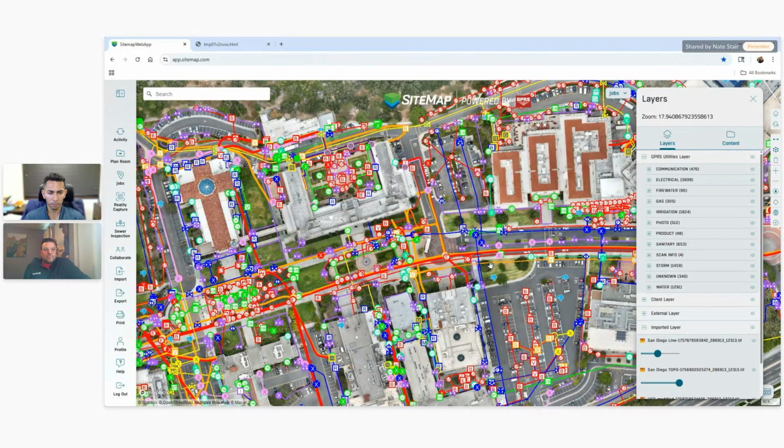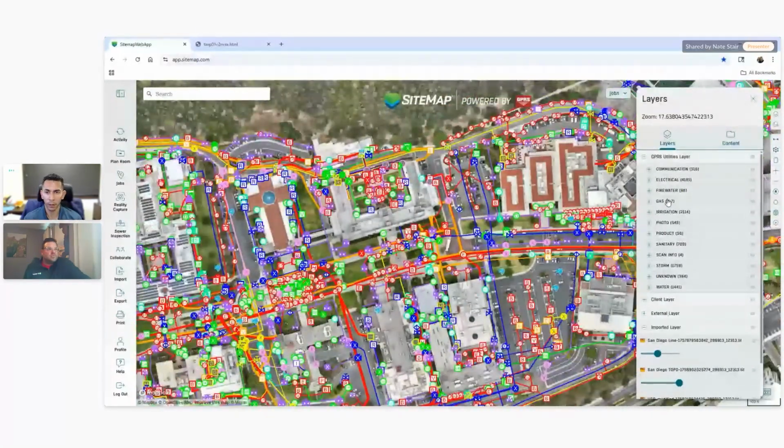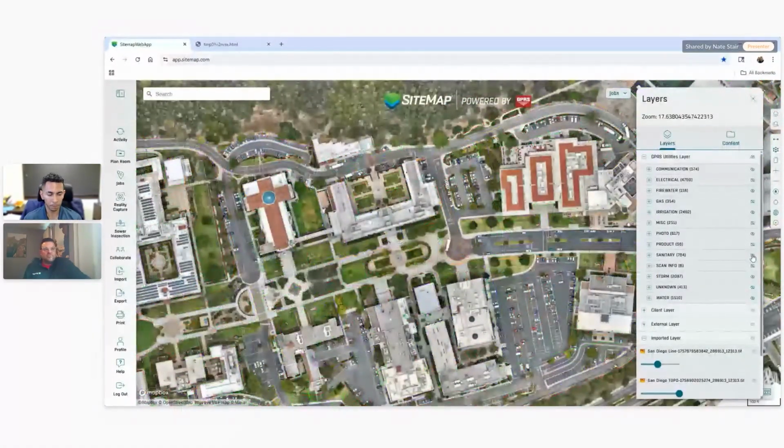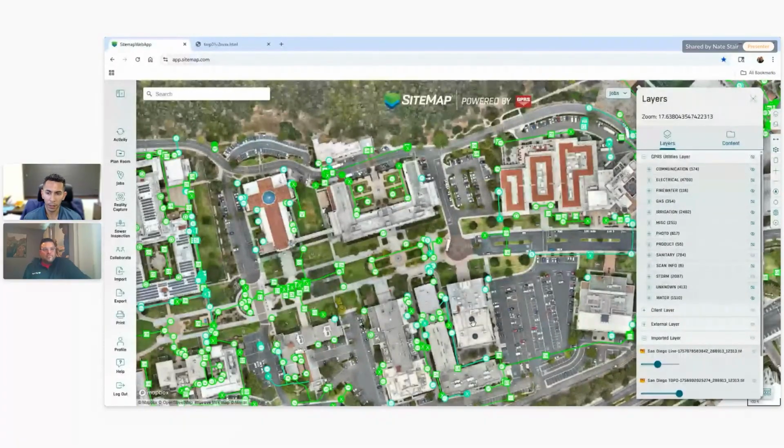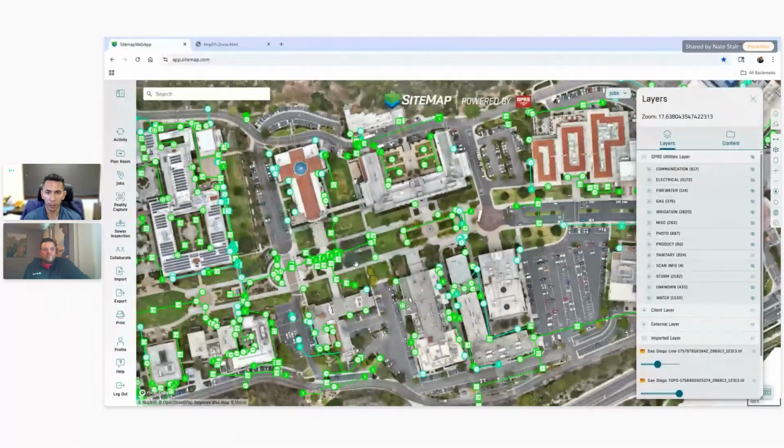We noticed that one of our pretty large storm drains was clogged, and the camera equipment we have wasn't long enough to feed through the storm drain and get a good view of it. So GPRS came out and dropped what looks like a little car inside of the pipe, and sent it down the direction where we suspected the clog was. Once they found the clog, we were able to identify exactly where it was, and then we have our own equipment that's able to clear those clogs.